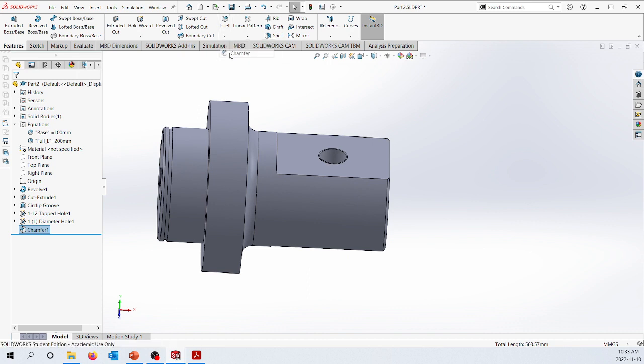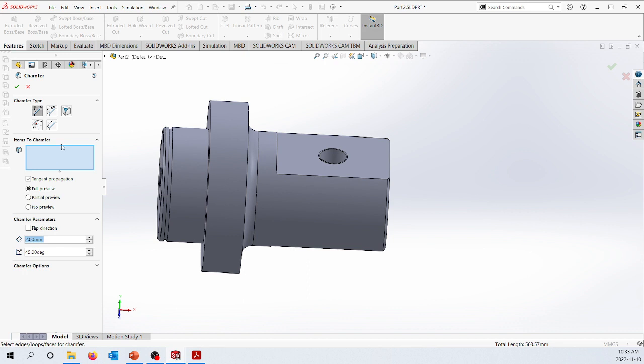I'm going to go back into the chamfer tool for a second just to point at some things. So you'll notice how we define our chamfer. We have a bunch of different options. The ones we're used to in AutoCAD, angle and distance, or distance and distance. We can have some weird ones if we're not at exactly coming at it at a nice angle. We can have assume even distances, but we want a specific length. We can have wacky corners not getting knocked off. If we just want to knock a corner off at a vertex. And that's basically it. That's your chamfers.